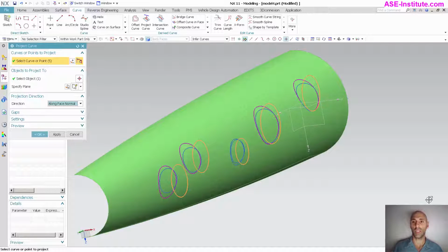Allows you to do things quickly. Again, this is great for sheet metal parts, composite parts, anything with lots of layers and plies. You may need to take a couple of the layers, flatten them out, put your shapes on there, wrap those shapes back into place. And so flattening and forming allows you to do that.